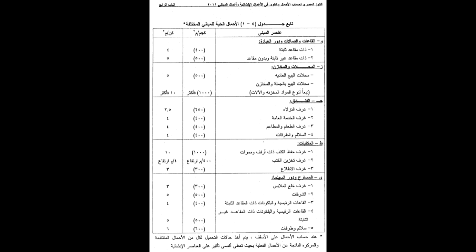The stores that sell wholesale, the load is 1000 kilogram per square meter or more, depends on the store type or material stored. For hotels, the rooms 200 kilogram per square meter. Public rooms 400 kilogram per square meter. The restaurants 400 kilogram per square meter. For stairs and corridors 400 kilograms per square meter.